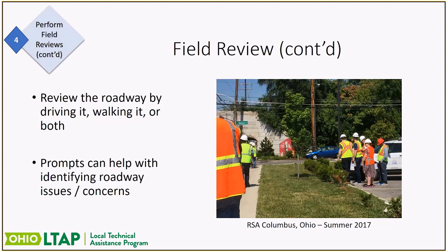But on this RSA that we did here in Columbus, one of the things we did as far as walking it is we were able to determine that the signal timing was off for a crosswalk. A number of us crossed the street a number of times in one section, and none of us could get across in the time that the signal had on it. So that was one of the recommendations, was to go out and retime the signal and the pedestrian crossing.